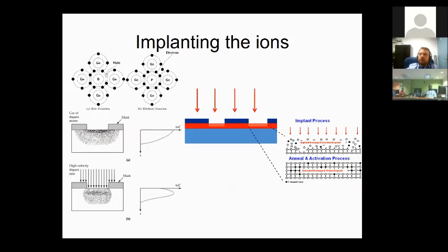Okay, so the ion implantation. We talked about different ways of introducing ions. These would be the dopants. The first immediate way was the diffusion, if you remember. We could diffuse them into the substrate, and we could dope the silicon that way. But look at the example. It's not really well controllable. Diffusion is not so controllable, so it will also go underneath the mask too.